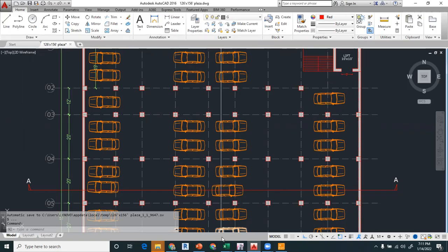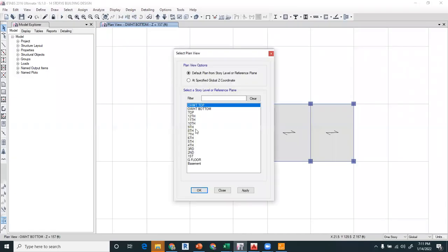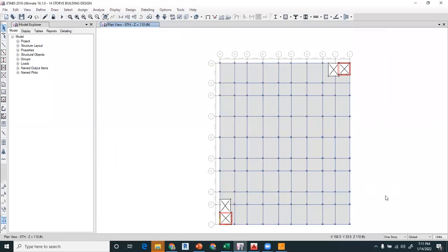Sobat Khan, sir. Okay. So he's asking that during the modeling of our structure, you have to select 1 story or all stories. It is in the right corner of the ETABS. You can see my cursor, that is a drop-down menu of one story, all stories and similar stories. We haven't used the similar stories command, but we will use this in the coming sessions. You will select it from here.